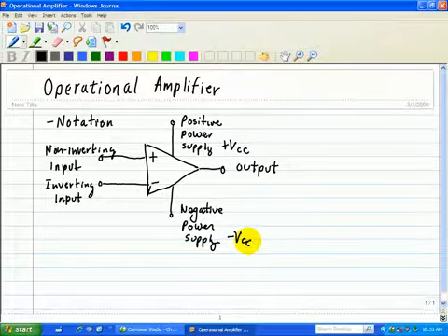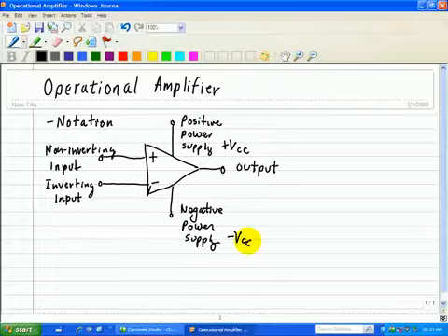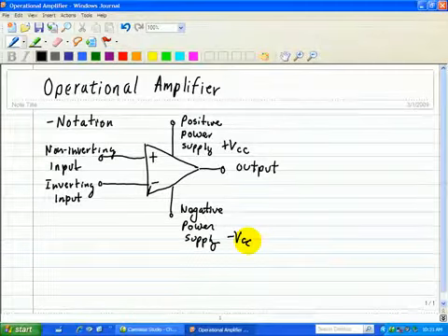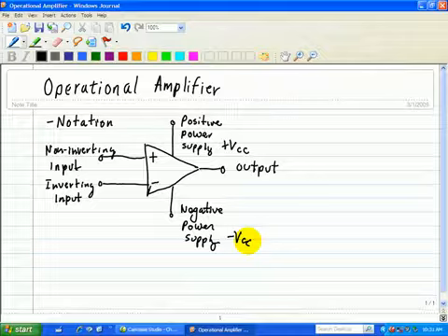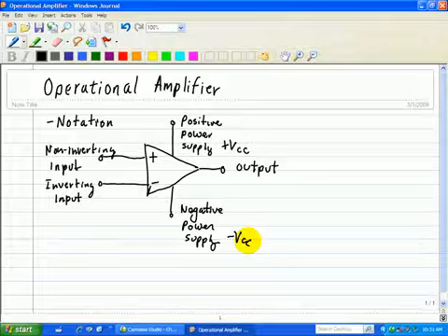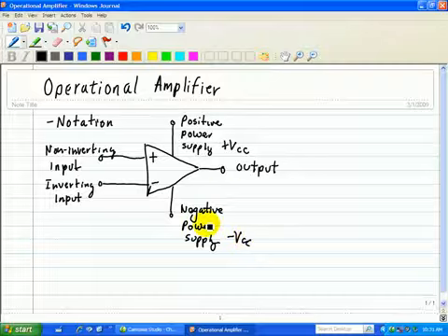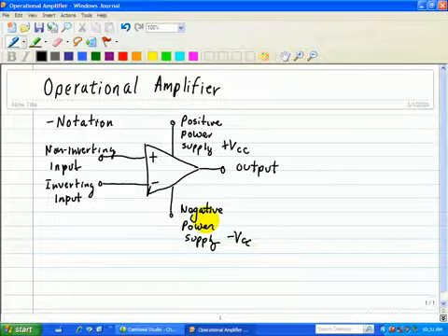While some op-amps have more than 5 terminals, these 5 are usually present and are the only ones we will use in this series of tutorial videos. The 2 power terminals shown here are not usually shown in circuit diagrams. However, be assured that they are always there because the external power supplies are required for the op-amp to operate as an active device. The power required for signal amplification comes from these terminals, from an external power source.